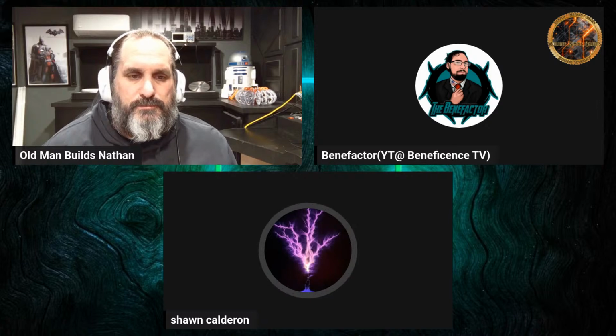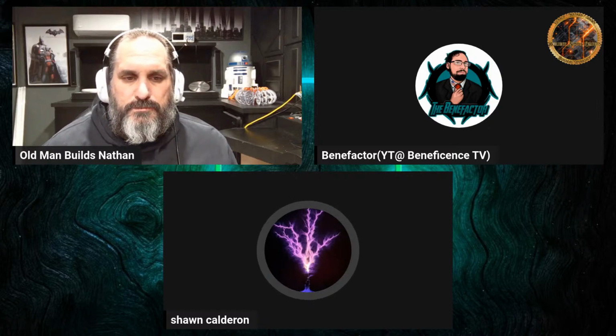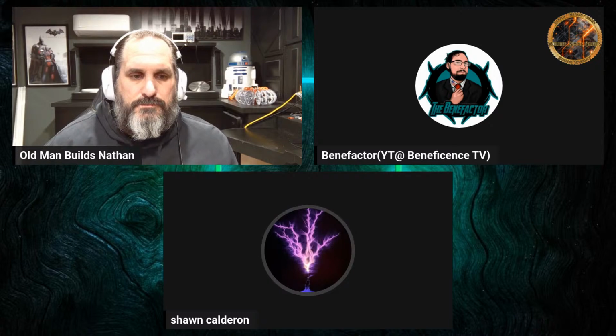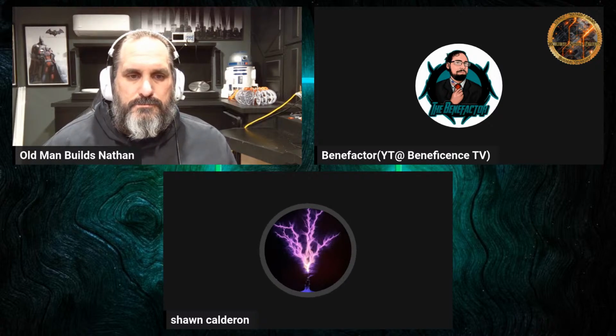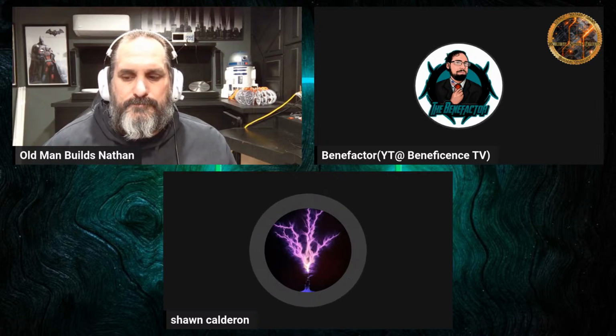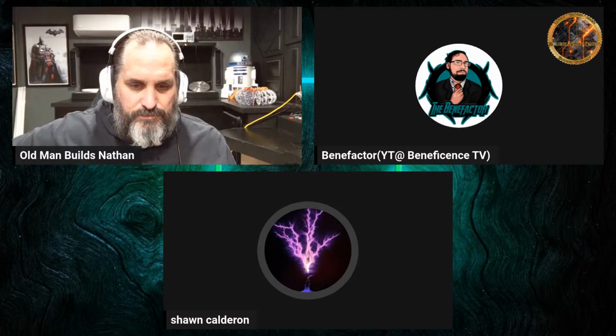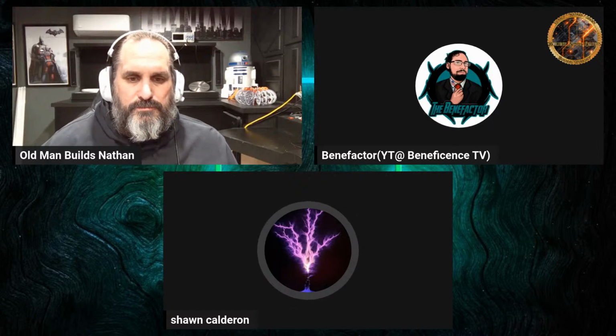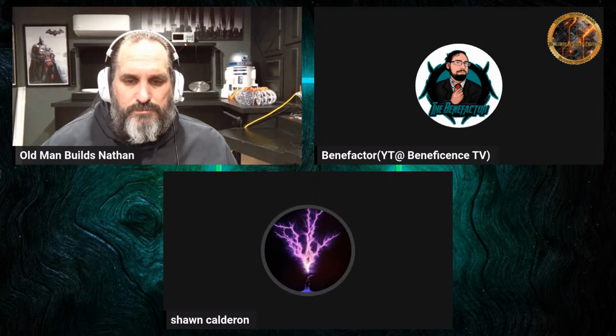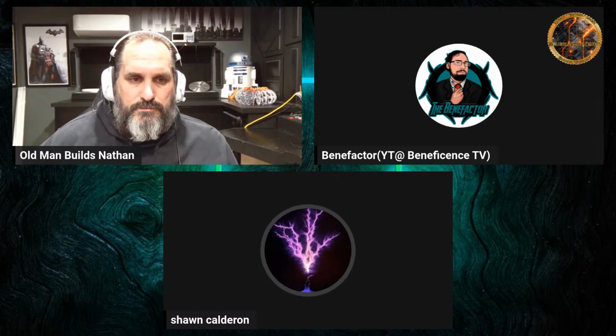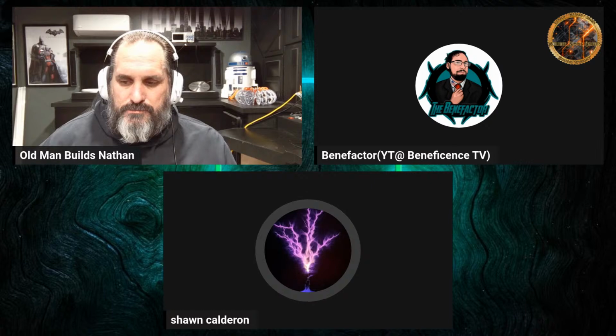That's the beauty, because the number 2 coil is literally connected to the base of the MOSFET or transistor. So whatever is the perfect resonant frequency of coil 2 is self-tuning to the base frequency of the transistor. That's amazing, because with the ZVS it's tough to get as close as the Slayer. But the ZVS has its positives, because you can throw some pretty big plasma or push some higher power radiant energy than the Slayer. The Slayer has a low ceiling on what you can do with it.